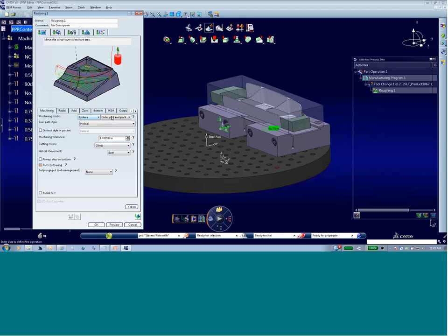A little bit of cutting information. I'm going to do one way outside and change the tolerance and give it a depth of cut and maybe turn high speed on, and that's good enough for this one. Hit replay.